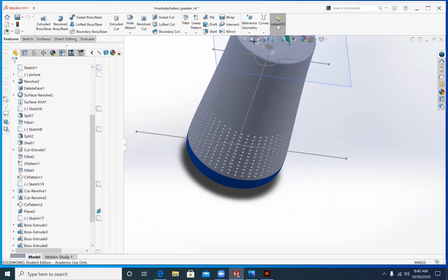I have one more question, like with the thing you said, I'm doing the Pathfinder thing. Even after doing a Pathfinder, do I need to join it or no? Yeah, I'm thinking that yes, that's a big lesson for us all today, is to join your line work after you've made it in Illustrator. We want that line work to be clean and joined. Another thing is that you should make sure that you join your interior lines and then also the lines that you make like the outside path, because you have to do both of those separately.